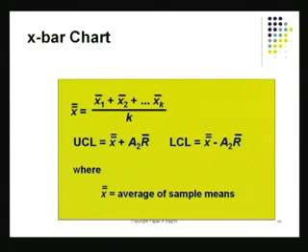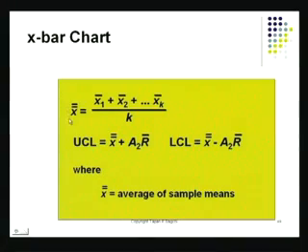Well, you have the formulas which are shown here, and finding the grand average of X bars is not that difficult. The overall average, which I'm showing here, is the average of sample means. Sample means are little X bar values, and I found X double bar, which is the average of these sample means collected over some history, maybe last 1 week's production or something like that. So I've got an idea of X double bar, which I use to find the upper control limit. I should really be doing X double bar plus 3 sigma X bar.